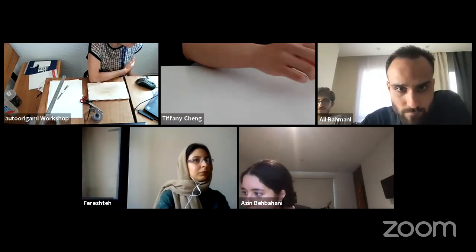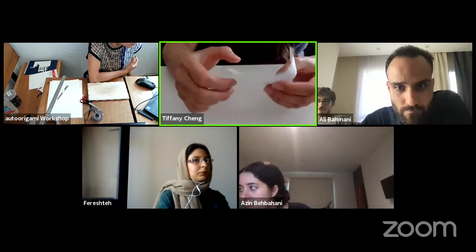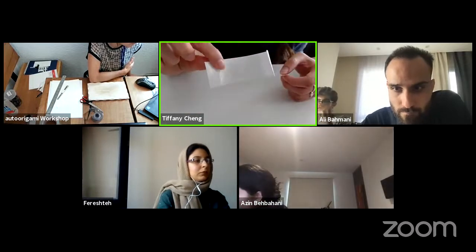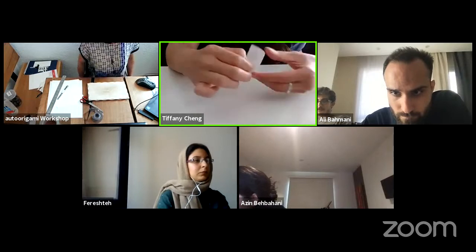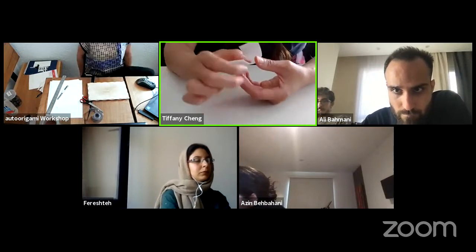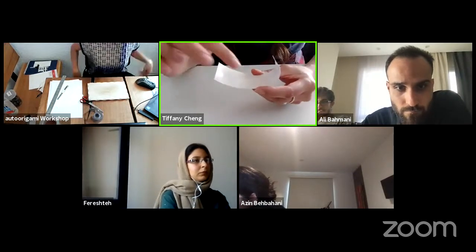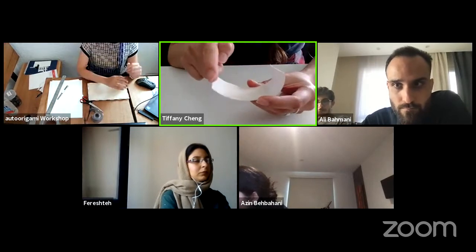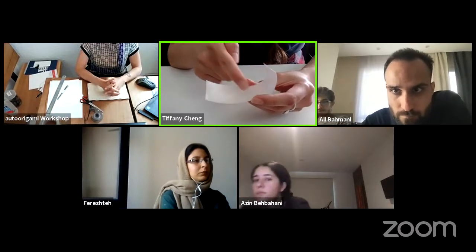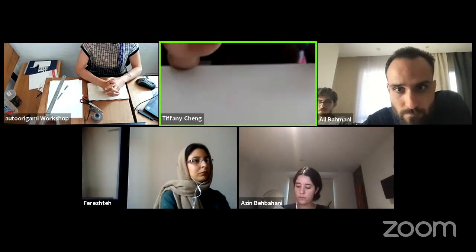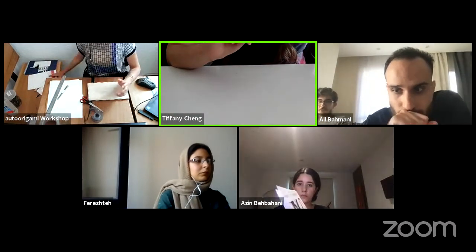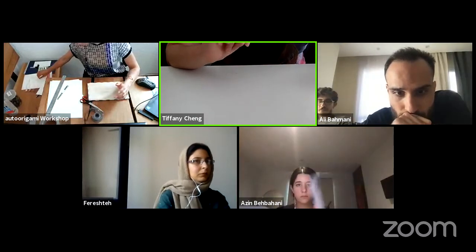Another technique to do this is to vary the amount of tape that is behind. By adding the tape, we're increasing the bending stiffness of the material. So here I have one layer of tape, 2 layers and 3 layers. That's also another technique that we have to change the bending magnitude across one part.